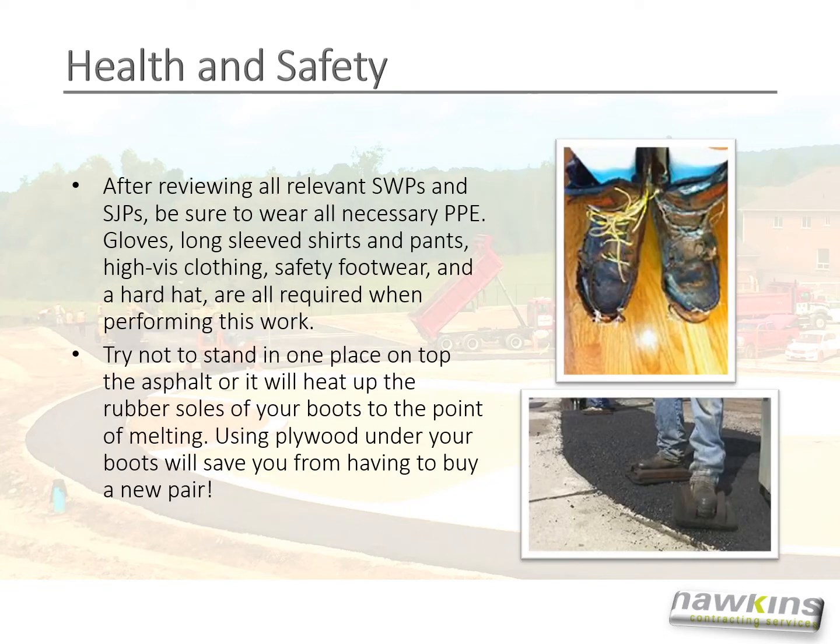After reviewing all relevant safe work practices and safe job procedures, be sure to wear all necessary PPE. Gloves, long-sleeve shirts and pants, high visibility clothing, safety footwear, and a hard hat are all required when performing this work. Try not to stand in one place on top of the asphalt, or it will heat up the rubber soles of your boots to the point of melting. Using plywood under your boots will save you from having to buy a new pair.